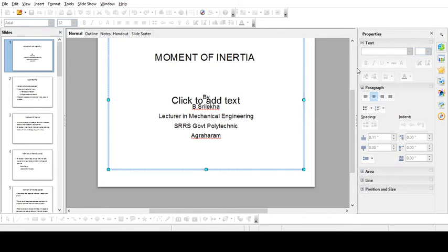So here, Iyy means Ig along the centroidal y-axis plus A into hx square. So it is simply the moment of inertia about the centroidal axis plus the product of the area and the square of the distance between the two axes.